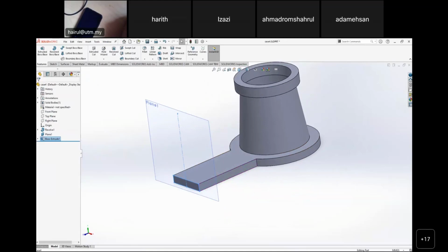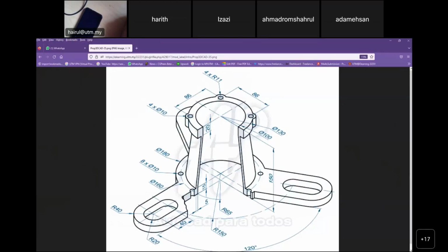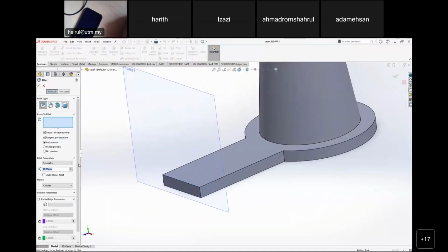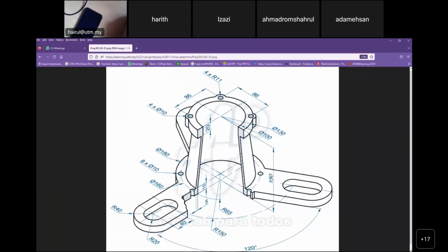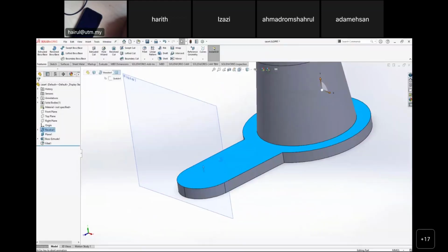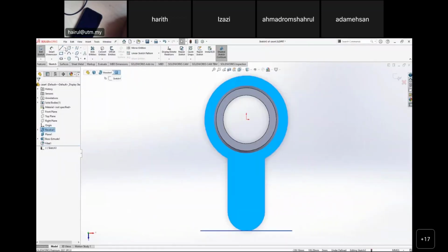Okay, this one is simply straightforward. Fillet, radius 40. This one we fillet, radius 40. So you fillet these edges and those edges, radius 40. Now be careful, after you fillet, you make a slot. You make a slot of it. And this one at the top surface, also I create a slot.